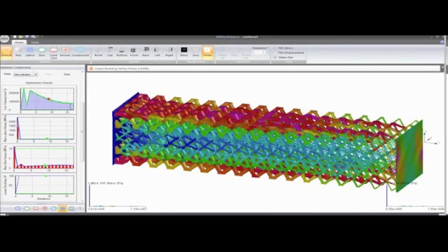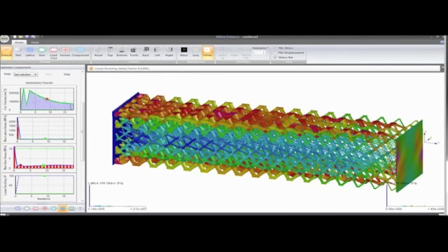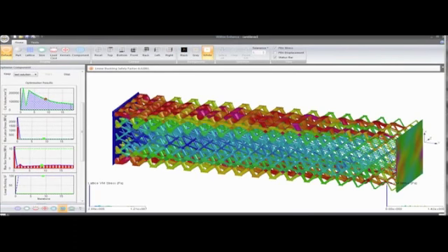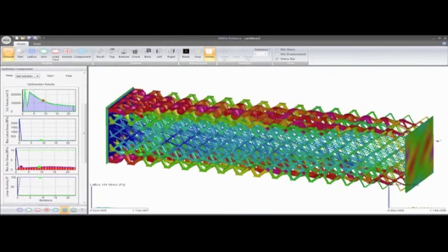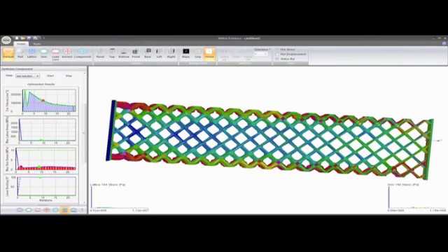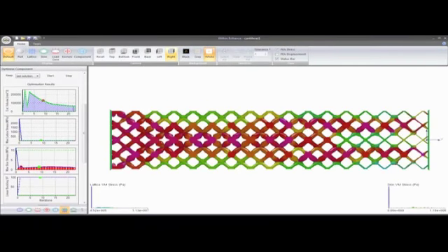If you were to manufacture this and CNC it, the more holes you make, the more expensive it is, because it's a subtractive process. In fact, the solid block is the cheapest thing. Anything you then do to it is adding to the cost. With 3D printing, it's the exact opposite. You start with nothing, so every little bit of powder of material you add to it is costing you more. So in fact, what you want to do is add as little as possible, and all this complexity, all these internal structures actually aren't really costing you much in computation or in time. So here you can see we made a component that has a slightly fluid and varying density structure that meets our requirements.